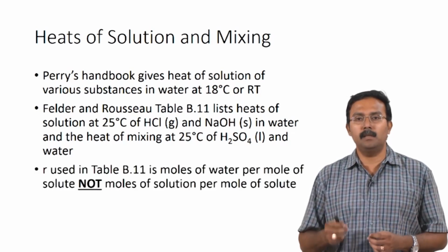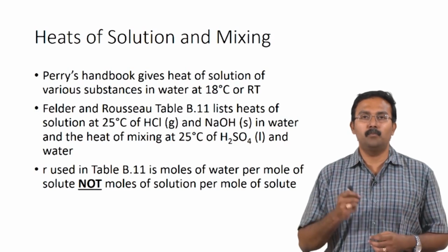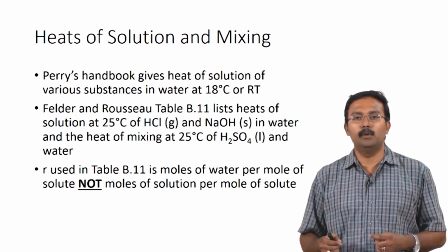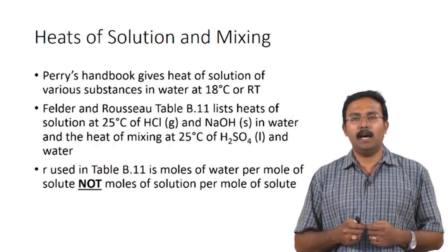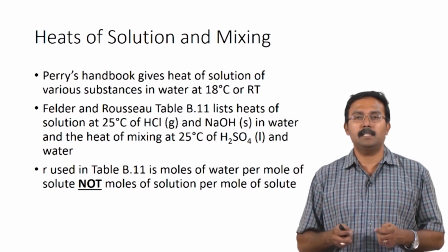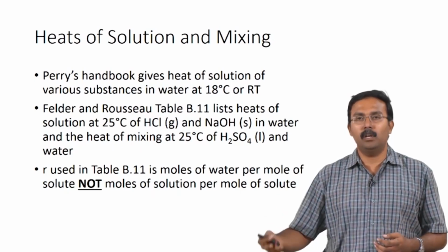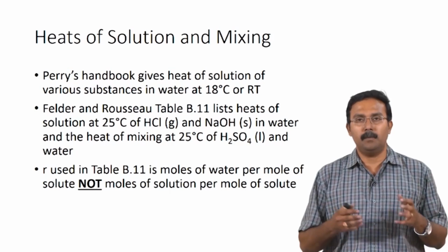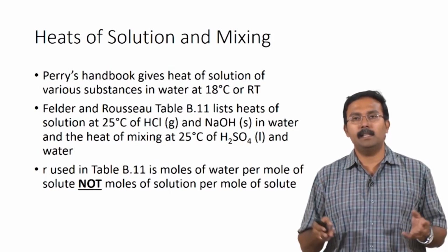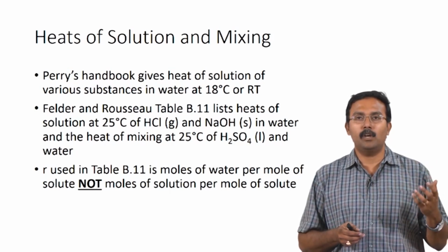R is used in the table B11 in terms of moles of water per mole of solute. It is not moles of solution per mole of solute. So, R is usually represented as the number of moles of the solvent, which is water, per mole of solute. Okay. So, use that appropriately, because when we write the enthalpy table, just like how we saw with psychrometric